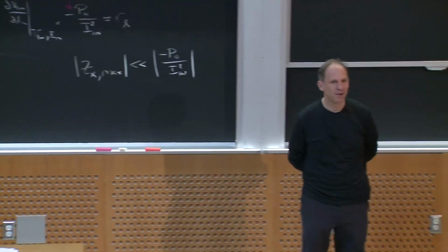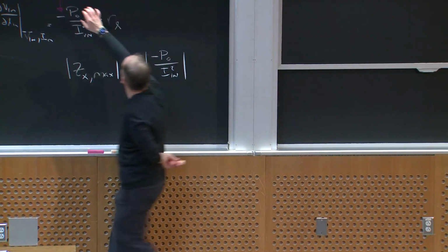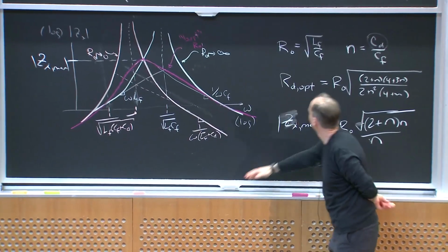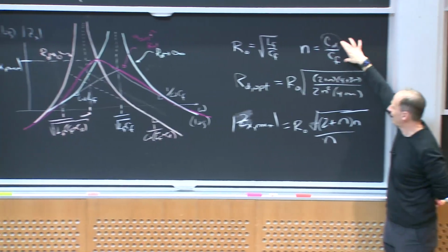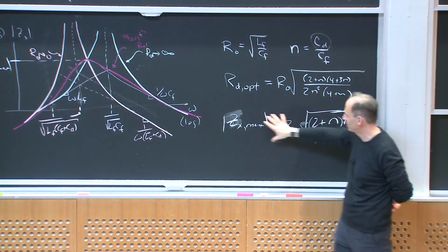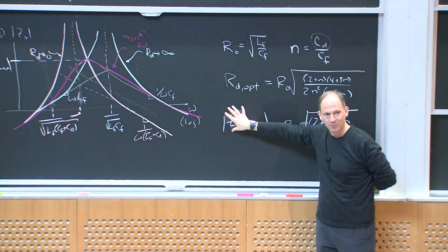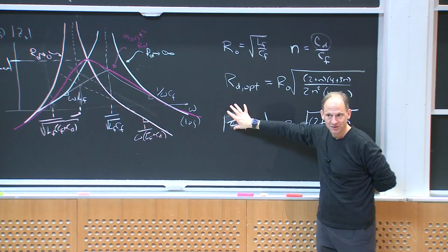So I've got to pick my damping, and that's going to drive me to pick some minimum. If I were to use this capacitive damping scheme, that's going to drive me to pick some minimum value of the damping capacitance so that I can minimize the maximum value of my filter output impedance across frequency. Does that make sense to everybody?